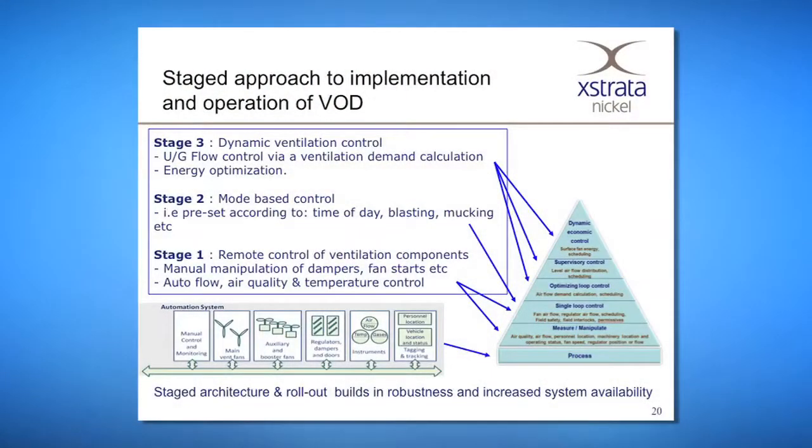So with this thinking in mind, the way we built our ventilation on demand, we built it and are running it in 3 stages. The first stage is just remote control of ventilation components. Now that name may not sound very fancy to people, but it really is. That in itself is quite a step forward for mining: you can sit on surface and adjust your ventilation components, so that's regulators and fans, and you can control that from surface. That's a great start.